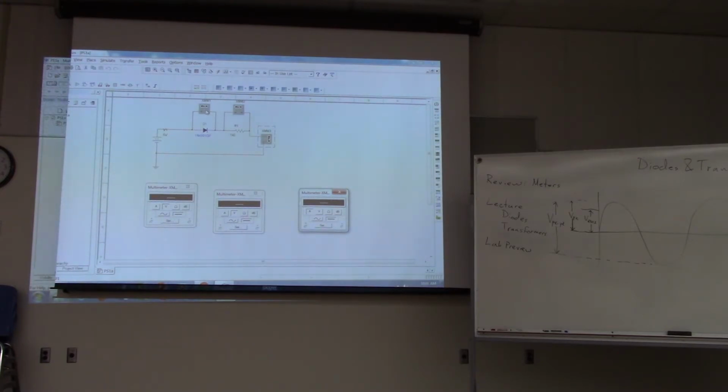Is that the voltage we're measuring between, or are we measuring the voltage through it? Well, voltage is always measured between 2 points. So we're measuring the voltage difference between one side and the other. Yeah? The diode is reverse biased because you're increasing depletion. Does that imply that the resistance goes up the larger the voltage difference with reverse bias condition or not? Well, so when it's reverse biased, essentially no current flows through it, right? So it has essentially infinite resistance. Yeah, it's like an open circuit. So you treat it just like an open wire or something. Yes, that's right.